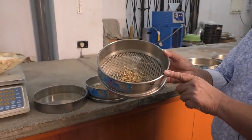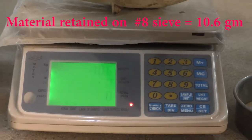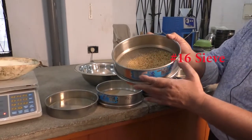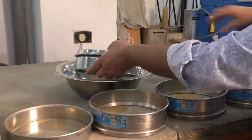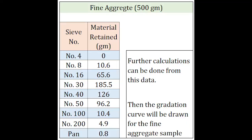Here we can see that some material has been retained on the number 8 sieve, the weight of which is to be measured now. In a similar manner, the weights of the material retained on all other sieves are measured. From this data, further calculations can be done, after which the gradation curve of the fine aggregate sample can be drawn. Now we will show the sieve analysis of the coarse aggregate sample.